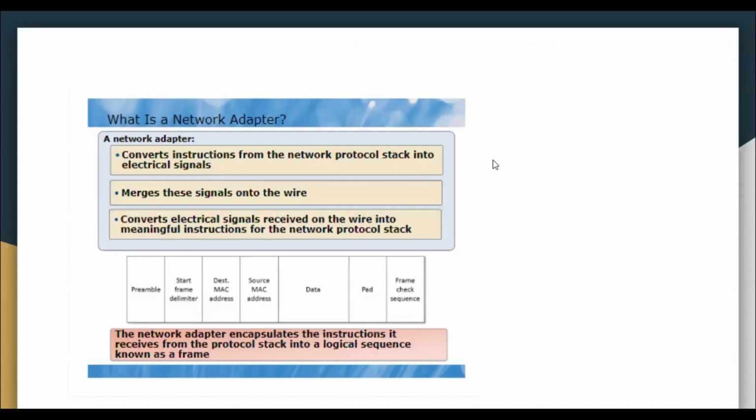Sometimes the SFD is considered part of the preamble. This is the reason the preamble is described as 8 bytes in many places. So the SFD warns the station or stations that this is the last chance for synchronization.